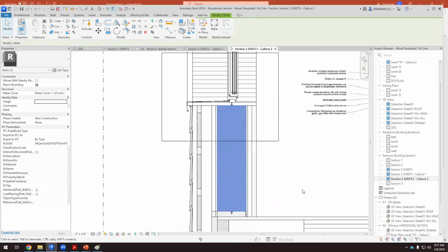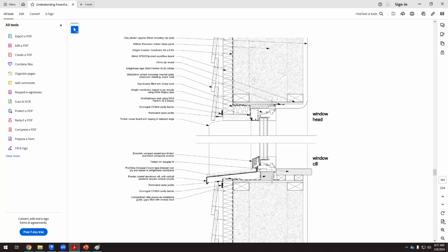I can even differentiate between the cellulose and the rigid insulation. And I think this is what we have here, okay? So we have two kinds of thermal insulation. This is the timber straw panel. It's not cellulose, but it's a fiberboard made of wood, okay? So they grind the wood and then they compact it. This is what they showed us in Benson Wood, this kind of thermal insulation. But it's different from this one. And this one is protect wood fiber board. Okay, it's not rigid insulation, but it's a different kind of insulation.